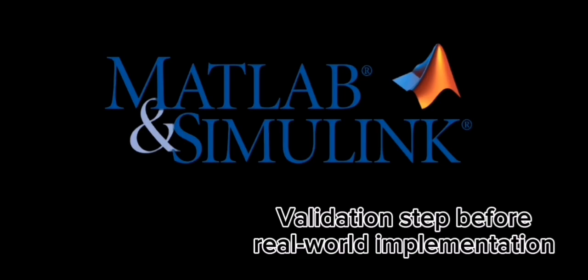Before implementing the real system on Arduino, we started with a very important phase: the modeling and simulation of the thermal system using MATLAB and Simulink. These steps allow us to understand the dynamic behavior of the room, to analyze thermal losses, and to compare open-loop control and closed-loop control with a PID controller. The simulation also enables us to validate the controller's performance before the real implementation.